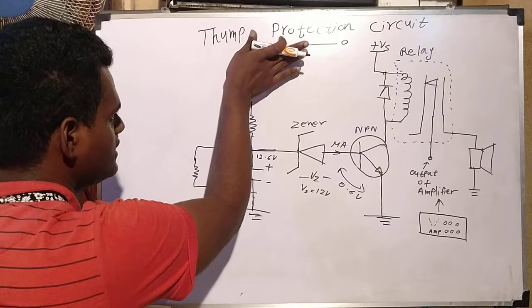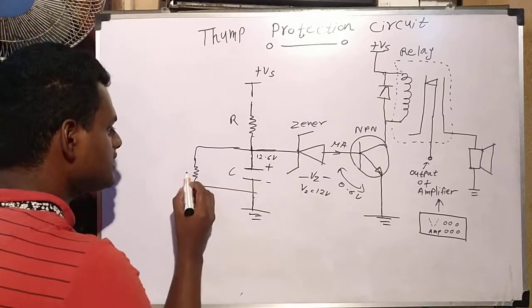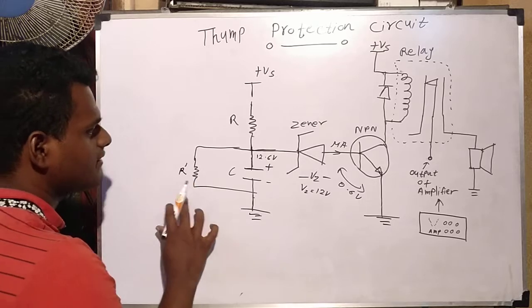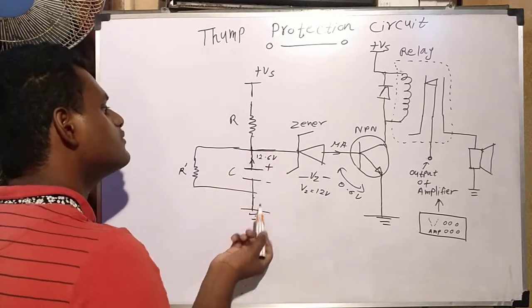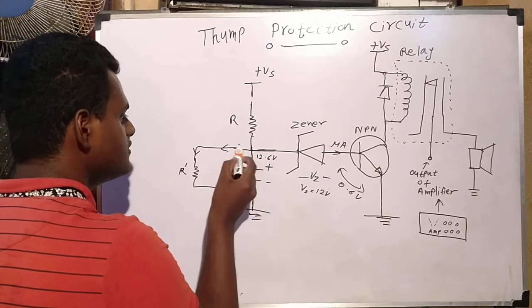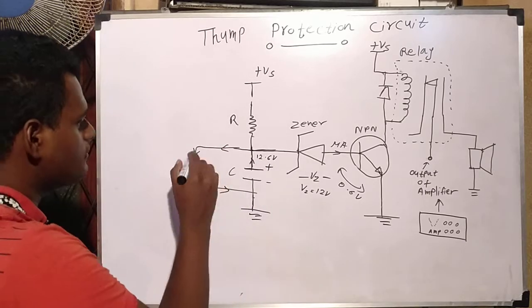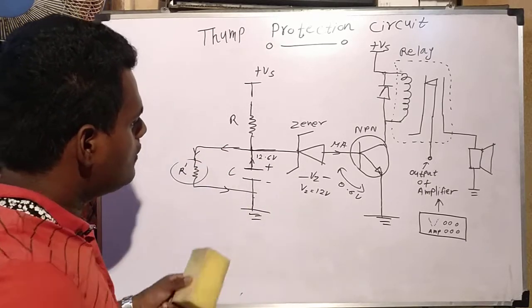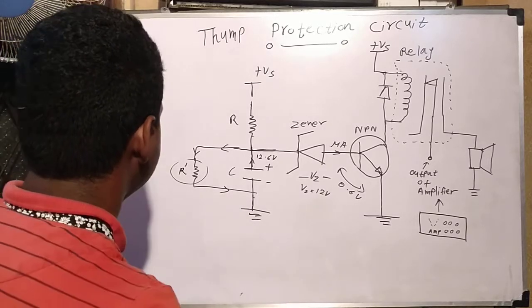What happens after the power failure? This power has failed now. Then there's no connection. If I take this as R C, then what happens? The capacitor gets to release its current, and it flows through this path. This path is flowing the current. Then it is totally dissipated by this resistor. So this is the basic method you can use for discharging the capacitor.